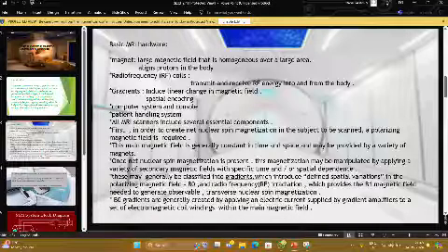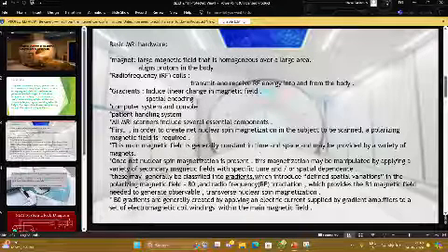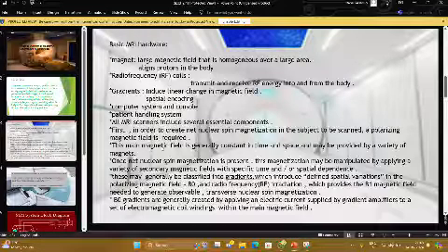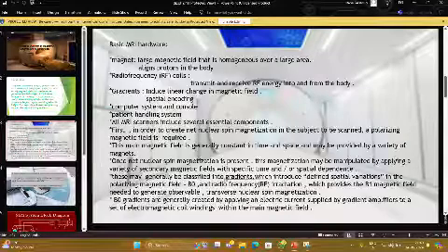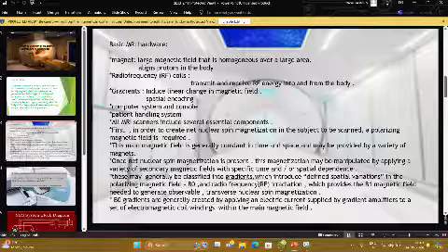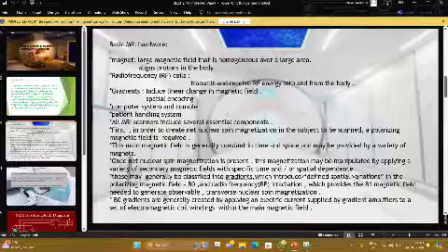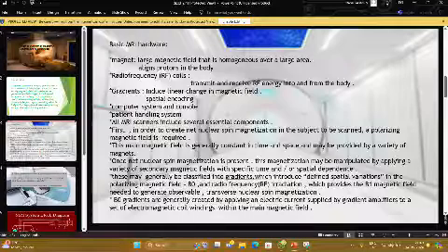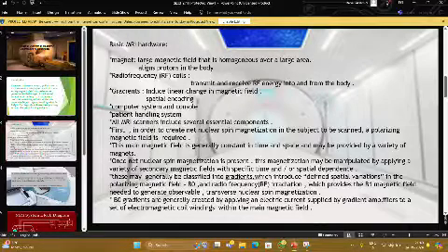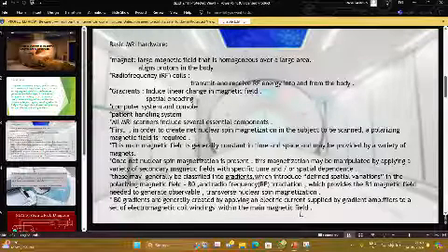First, in order to create net nuclear spin magnetization in the subject to be scanned, a polarizing magnetic field is required. This main magnetic field is generally constant in time and space and may be provided by a variety of magnets. Once net nuclear spin magnetization is present, this magnetization may be manipulated by applying a variety of secondary magnetic fields with specific time and or spatial dependence. These may generally be classified into gradients, which introduce defined spatial variations in the polarizing magnetic field, that is B0, and radio frequency, RF, irradiation, which provides the B1 magnetic field needed to generate observable transverse nuclear spin magnetization. B0 gradients are generally created by applying an electric current supplied by gradient amplifiers to a set of electromagnetic coil windings within the main magnetic field.